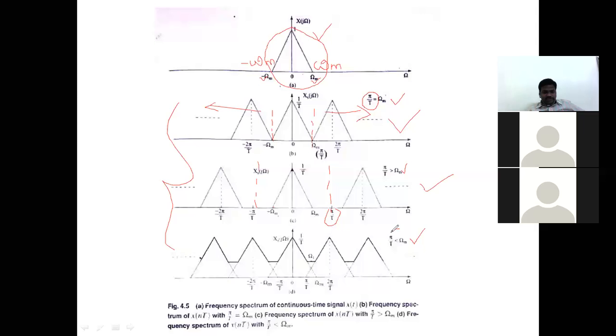But as far as the third case is concerned, now see here. You miss this data, a straight line. Whenever you find this type of waveform, these are distorted waveforms, and you lose the data in between two consecutive samples if you select the frequency less than the cutoff frequency. So this is the graphical representation for explaining the sampling process, going through the frequency ranges we have selected to get the original data. Those frequencies are very, very important. So always remember that the sampling frequency must be greater than or equal to twice the maximum frequency in the signal.